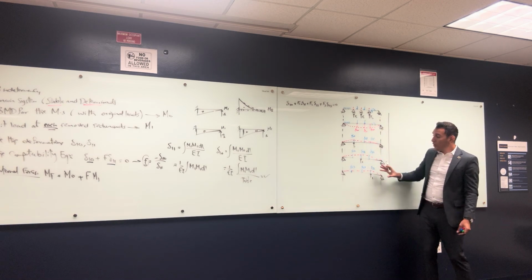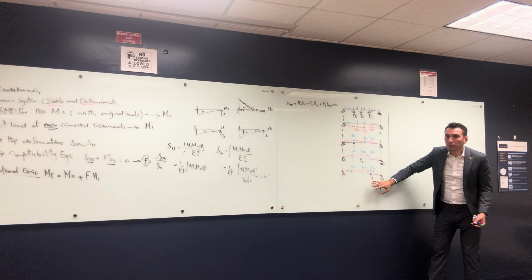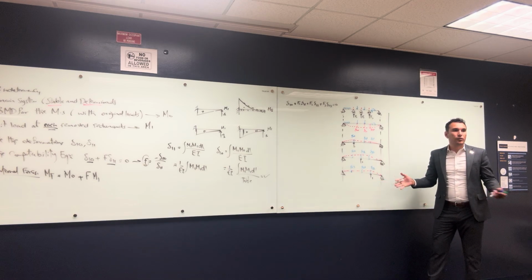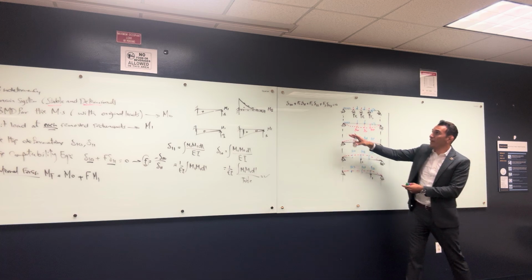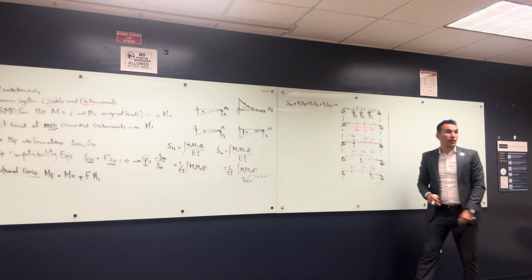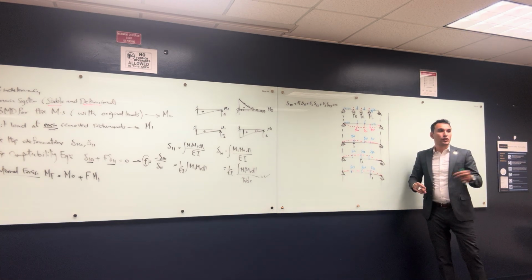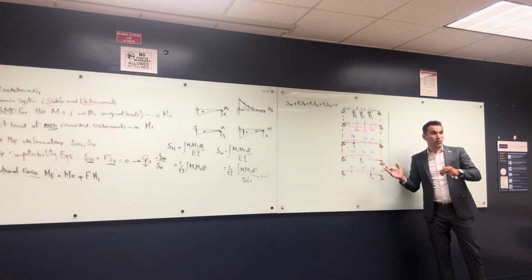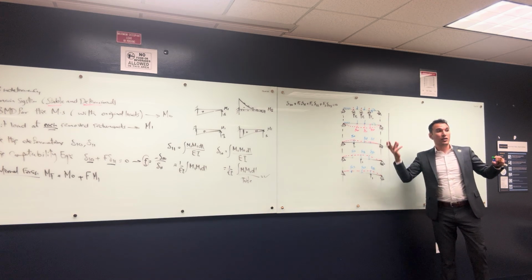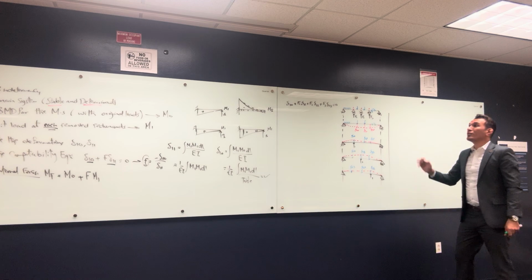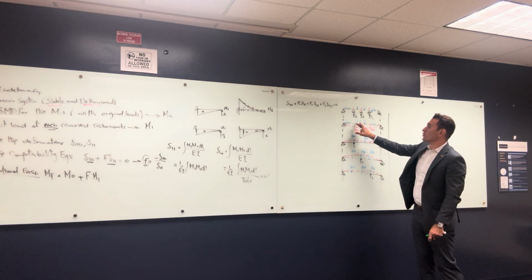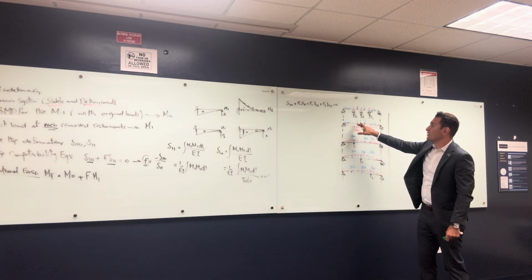So at the end, this one should be multiplied by F, but we don't know F yet. So that's why we'll put a unit load and keep F outside as a constant. Because you can draw the deformation from a unit load, but you can't draw it from F, because with F you are going to make your entire problem a function of a variable. It's going to make it difficult. So we take F as a common factor, and we get the deformation from 1. So this is only equation 1, because we know that the support number 1 has 0 deformation.